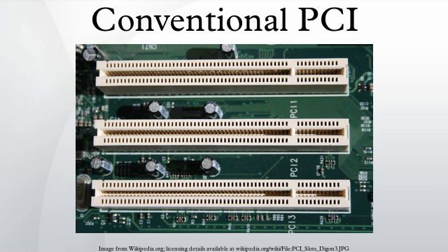TDO is daisy-chained to the following slot's TDI. Cards without JTAG support must connect TDI to TDO so as not to break the chain. PRSNT1 and PRSNT2 for each slot have their own pull-up resistors on the motherboard. The motherboard may sense these pins to determine the presence of PCI cards and their power requirements. REQ64 and ACK64 are individually pulled up on 32-bit only slots.